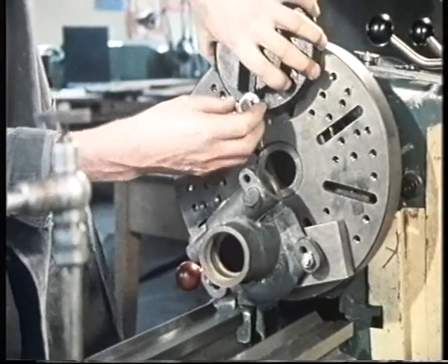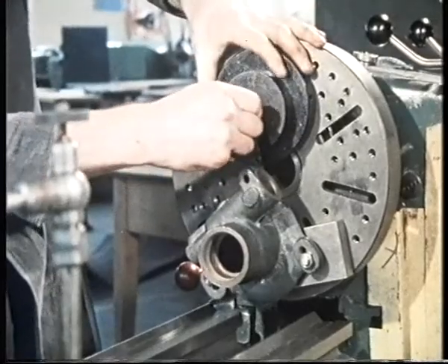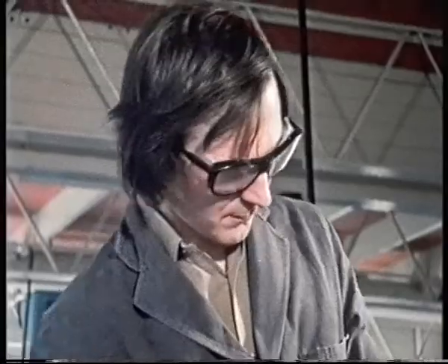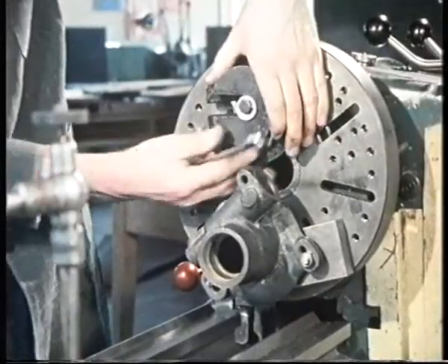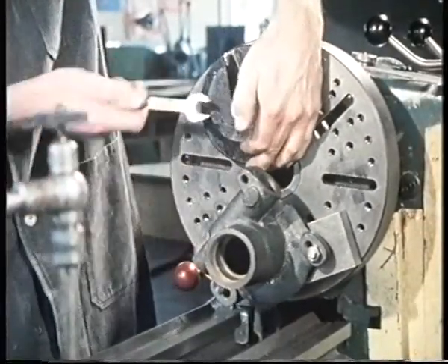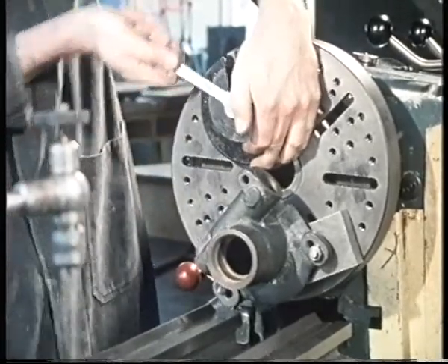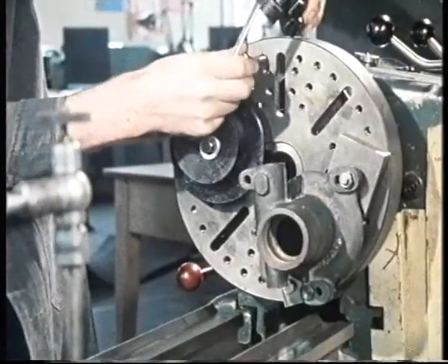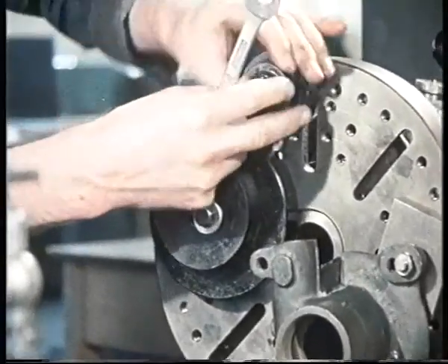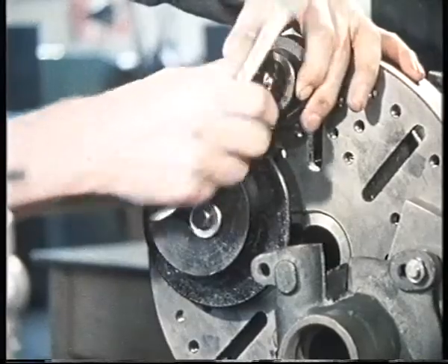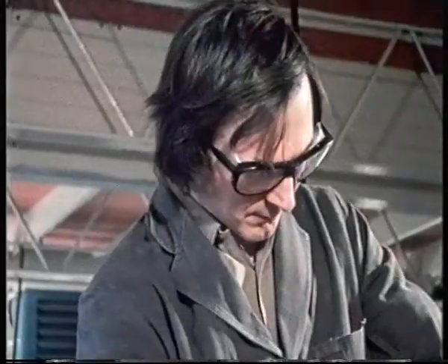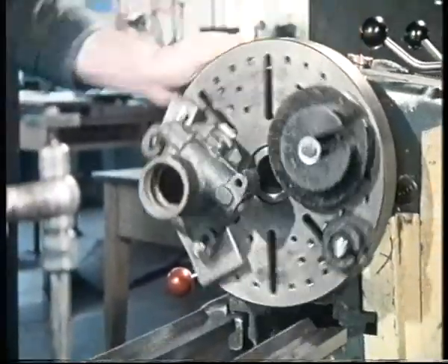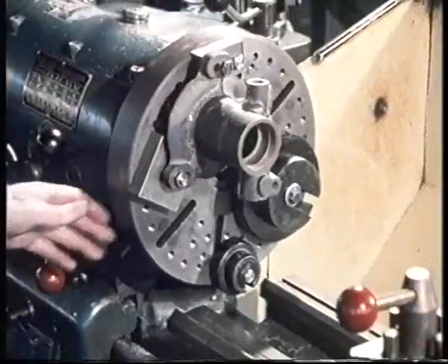If you have to use a slotted weight, you should never fasten it like this with the open end towards the center. Can you think why? For this particular casting, we found we needed 2 sets of counterweights. What we're doing here is to balance out the weights on both sides of the spindle. Now it's balanced.